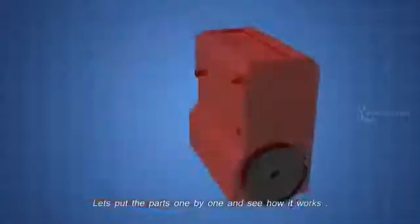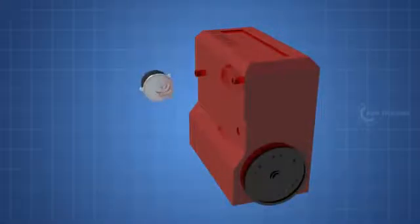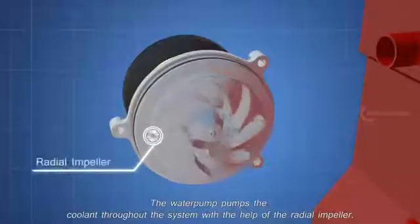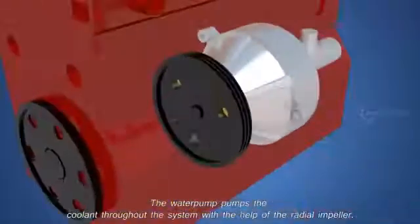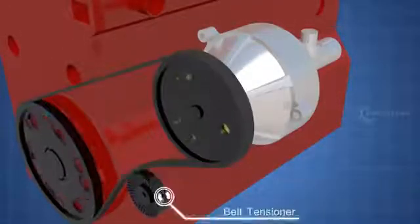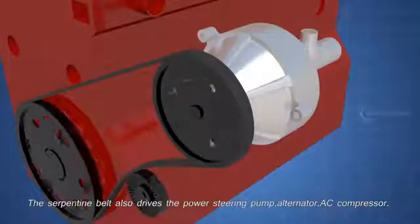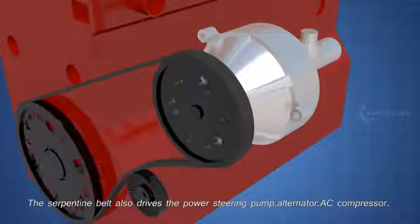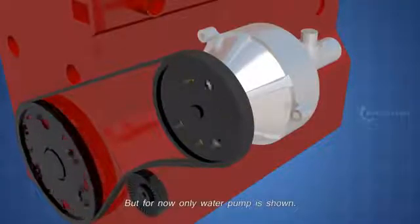Let's put the parts one by one and see how it works. The water pump pumps the coolant throughout the system with the help of the radial impeller. It is driven by the engine itself, using a serpentine belt. The serpentine belt also drives the power steering pump, alternator, and AC compressor. But for now only the water pump is shown.